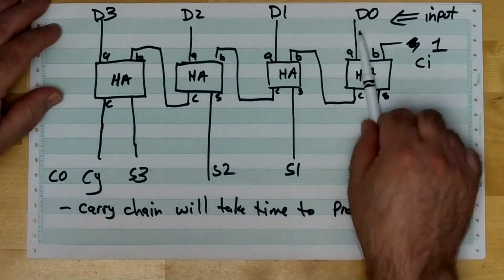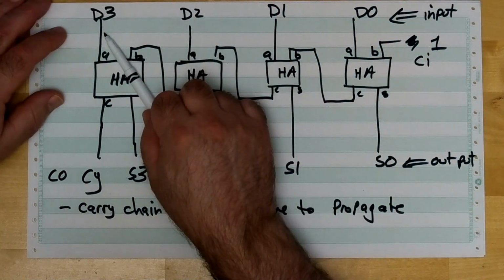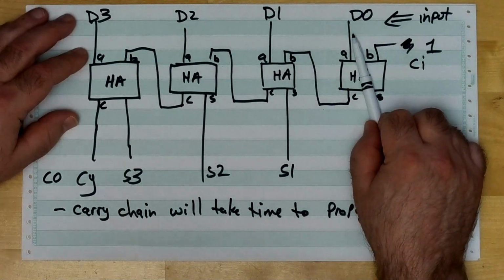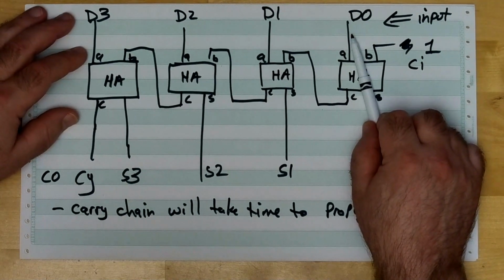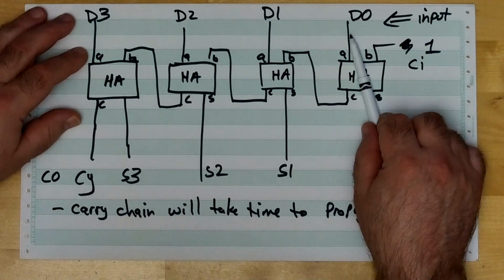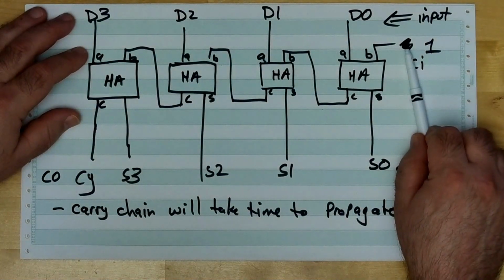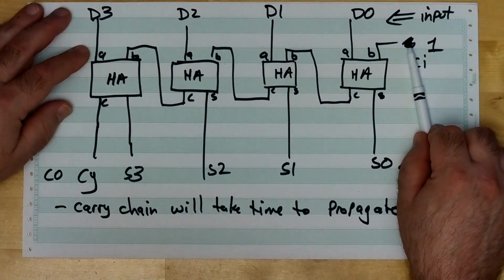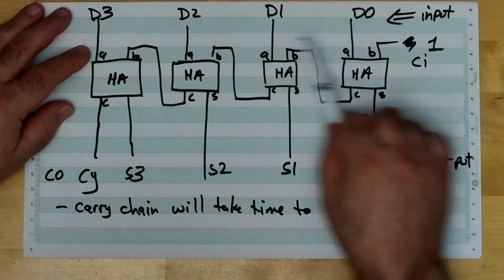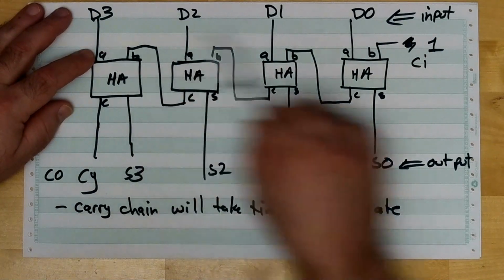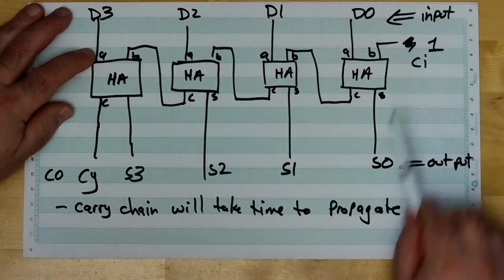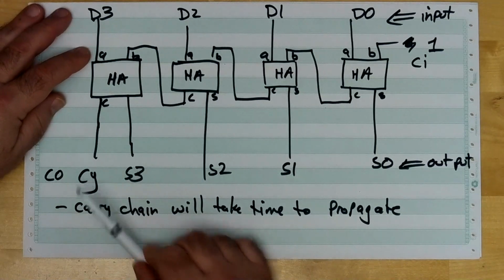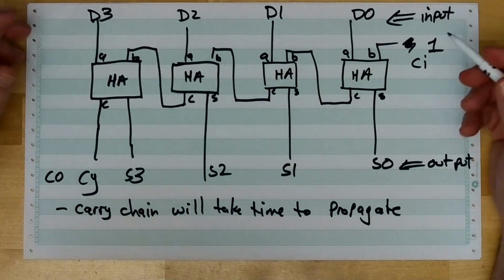Because we know that if all the inputs here are 1s, if it was an unsigned binary number, that would represent 15 in decimal, or F in hex. If you add 1 to F in hex, you get 1, 0 in hex. Well, that means 1, 1, 1, 1 plus 1 would be 0, 0, 0, 0 with a carry. So how would you draw up this truth table?